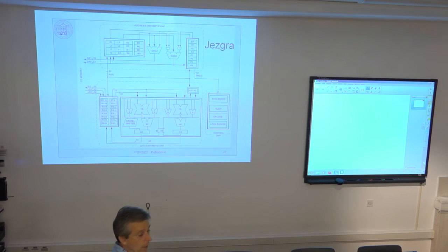I take one pixel from one image, the same pixel from another image, and then I add the two 8-bit values together and get the result of image addition. And by having these 8-bit adders, I'm capable of processing 8 pixels at the same time. Not 4 pixels at the same time. Okay, and that is the concept of single instruction, the same operation, addition, but multiple data. I have a vector of 4 8-bit values here, another vector with 4 8-bit values, and I get the final result.